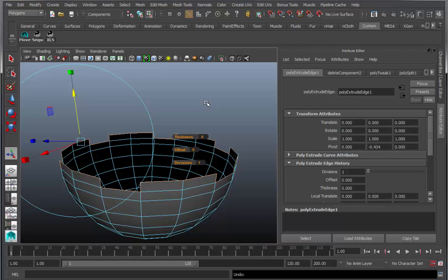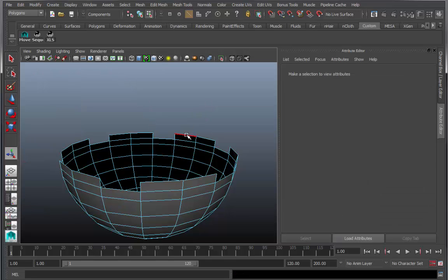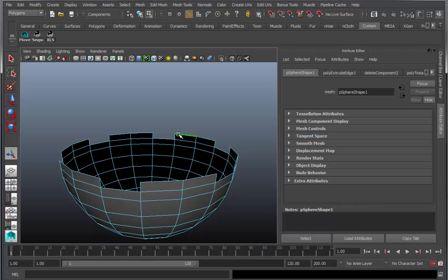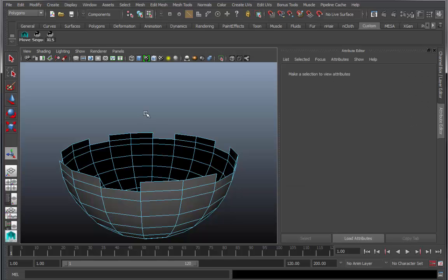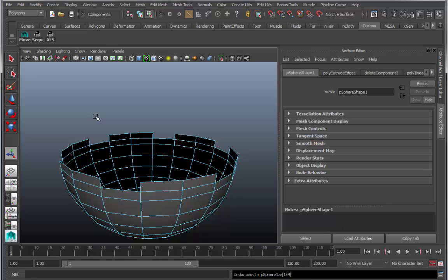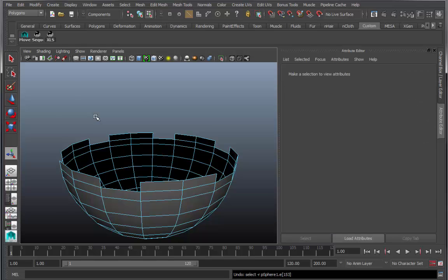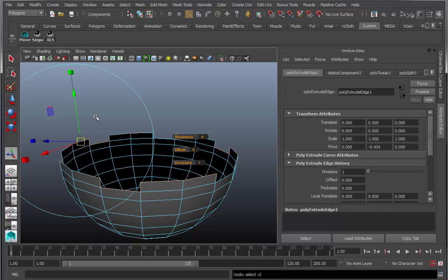Were you to click off here somewhere, big no-no, you'd say, oh, let's do it again. Double click. And wait a minute, the double click doesn't work. No, it doesn't work because you've got double polygons occupying the same space. And you can't see that because the modeling window doesn't really show it to you. So I'm going to press undo about a couple of times until I go back to that control. By the way, I don't recommend pressing undo when you've made a mistake.